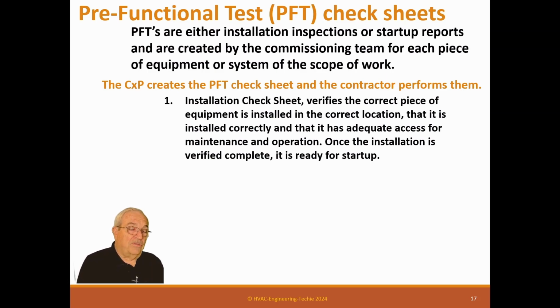So one thing, I don't know if you caught in the beginning of this, process commissioners will say that the contractor makes his own check sheets and does them, and the commissioner is really not responsible for any of that except showing him how to do that. The problem I found with that is a lot of contractors, their field technicians only know a piece of the system. They don't know it all, and they may not understand how to create a check sheet. Now, I've always told subcontractors, if you have a system that you've developed in-house to do all this, then give me a copy of it so I can actually see if it's robust enough. And 90% of the time, it is not.